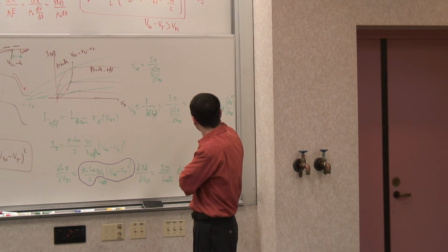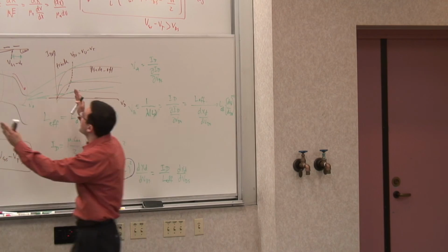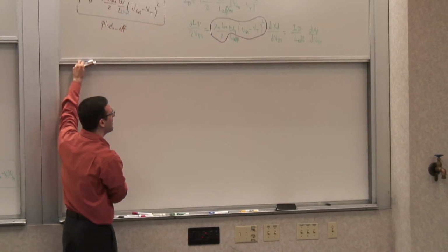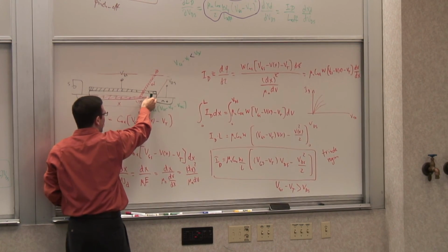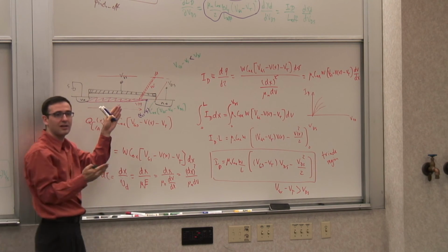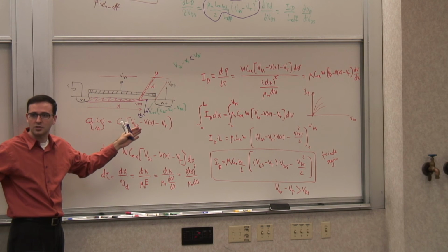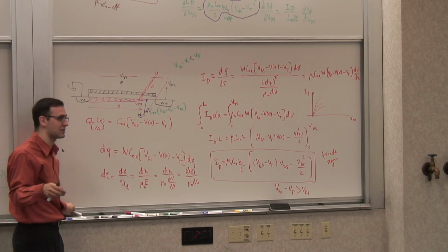What happens is that you have a larger channel. So the same change in VDS results in the same change in this length, this XD, but the total fractional change in channel length is smaller, because it's now a smaller fraction of a larger channel length. So does that mean that we want to make the transistor channel length as large as possible?